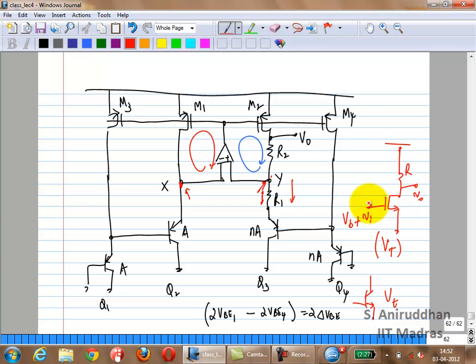First of all, let's take mobility. I think it's a little bit easier because what is going to happen to mobility? Decrease. Why? Because T to the power minus 3/2, what we wrote. But can you think of a physical reason why? Scattering becomes larger. Even though the particles have more energy, the energy goes into the random portion of movement rather than the systematic portion which you are interested in. So mobility will definitely decrease.